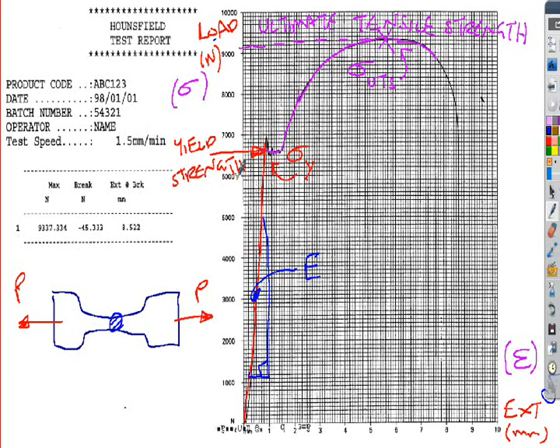One other point I would mention is the yield strength is sometimes called the proof strength. If I do another diagram here of stress against strain, curved materials often do not show this sort of blip in the structure. Most materials I've ever seen in industry actually have a continuous curve before they fail, so you don't get a defined yield point. So what engineers sometimes do is use what they call a proof stress, sometimes called the 0.2% proof stress, where they draw a line at 0.2% strain.